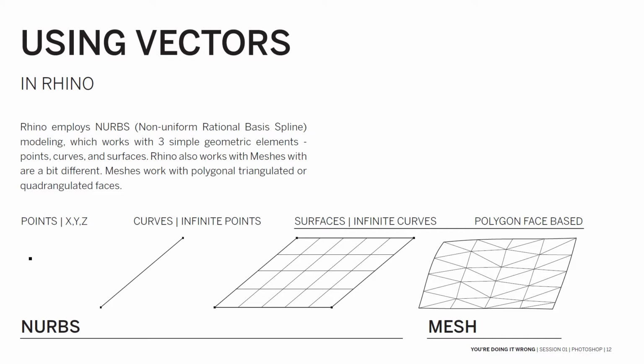And then another type of geometry that Rhino can edit but is not NURBS geometry is called the mesh. Meshes are basically polygonal faces that are combined together. So they're either a triface or a quad face, which means 4 points. A triface uses 3 points. And a lot of three-dimensional modeling actually uses mesh modeling to create it.